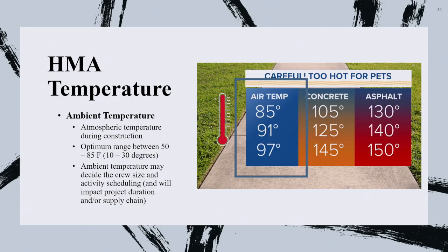So this could be an option if you do a project in remote locations in Nigeria where you can't have an asphalt plant close by, or the distance is huge to the point that you'll have a major drop in temperature. Instead of doing the pie crust thing and ending up with tremendous raveling, probably pay the extra penny. Usually warm mix is about 10% higher because you're adding emulsions to compensate for that drop in temperature, but it's worth it.